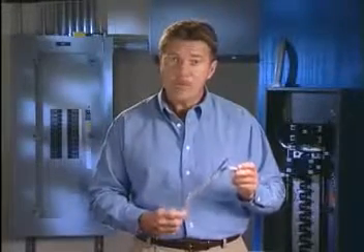The conductors of each circuit should be protected to prevent a greater amount of current from flowing in the circuit. Current flow generates heat, and increases in current will result in more heat. This excessive heat can cause the wire's insulation to melt, possibly causing a fire. Stopping the current flow will prevent overheating.